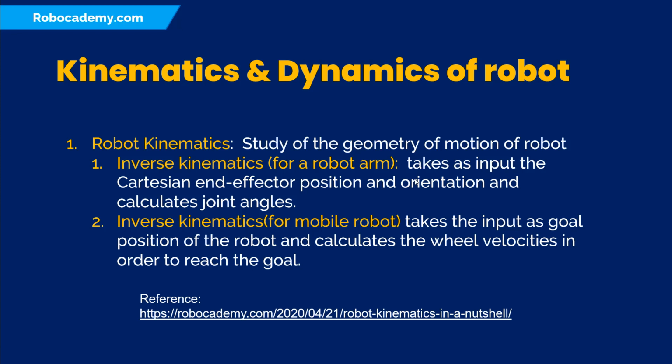There are many methods to reach a position. For example, this is the goal position and my hand, the robot arm, has to go to this position. I can move my hand in different ways, like this, like this, like this. So from the inverse kinematics equation we will get many solutions for the joint values. We have to optimize it somehow to find the best path, the best joint values.